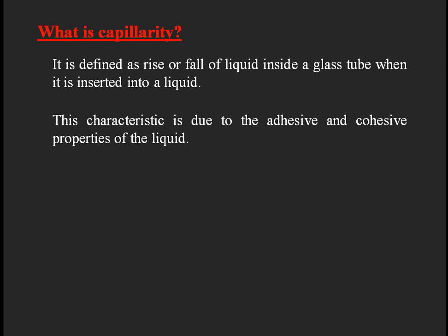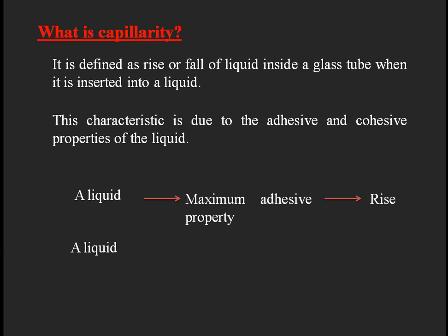Due to the adhesive and cohesive properties of the molecules of the liquid, we'll be facing the rise or fall of the liquid. When we get the rise and when we get the fall: if a liquid has maximum adhesive property, adhesive meaning the sticking property of the fluid particles or molecules to any other external body, in that condition we'll be facing the rise of the fluid inside the glass tube. Similarly, if a liquid has maximum cohesive property, we face the fall of the liquid inside the glass tube.